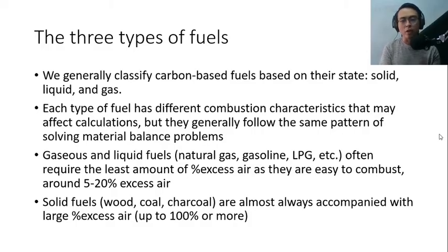Now, you might argue that if we increase the percent excess air, we would get a more complete combustion. Well, technically that is the case, but one thing to remember is that combustion reactions like this are normally useful in industry as sources of energy. And the main source of energy coming from combustion is the heat energy.